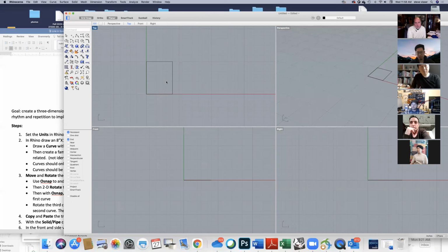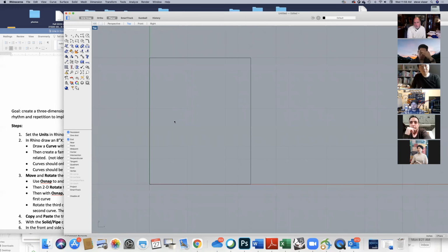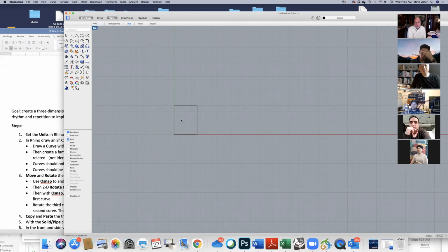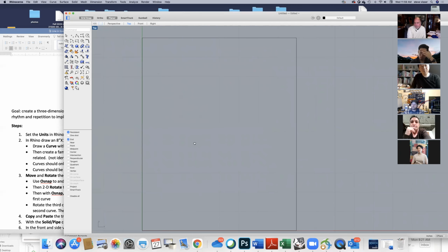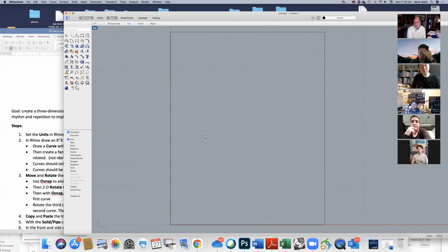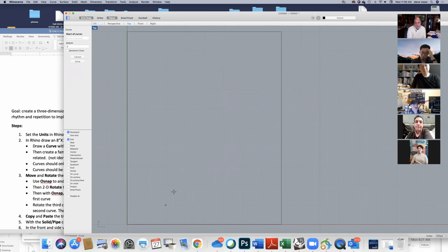Now, as I'm creating arcs, let's go ahead and double click on this. To zoom in, it's just the wheel. Wherever your cursor is pointed is where you will zoom away from or towards. If you right click, you can get the pan and move the page around. All right, so now we're ready to draw our 3 control point curves. Now I'm still using snap.